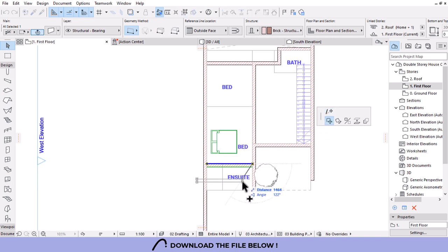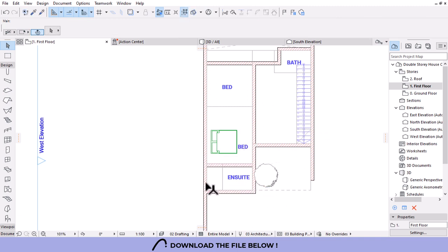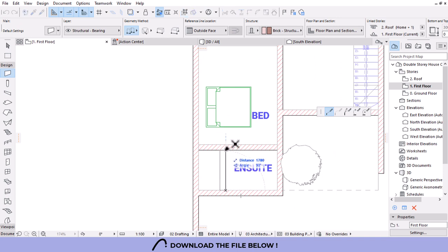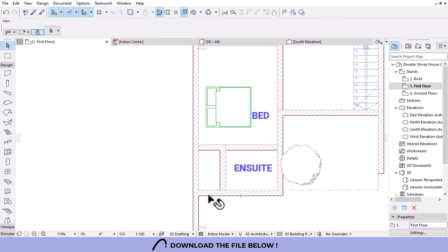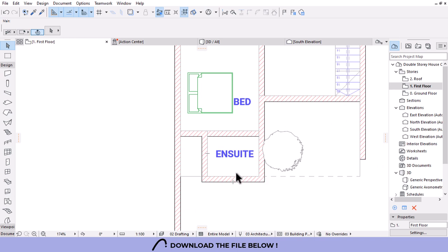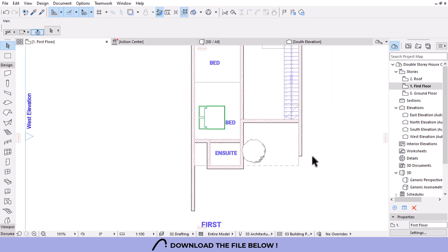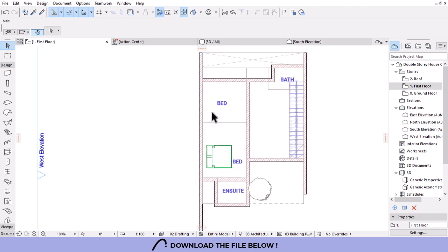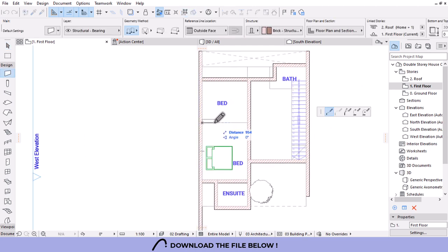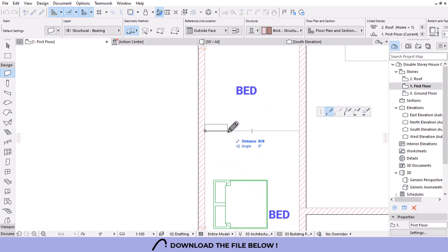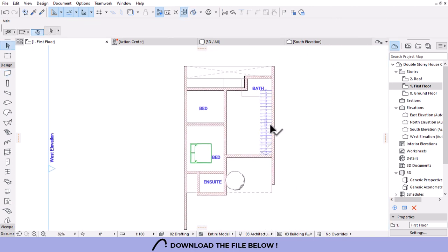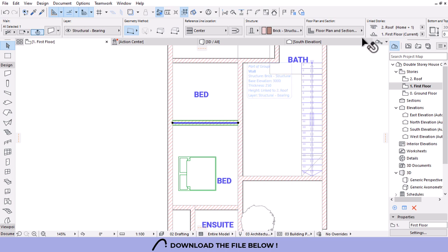and then I'm going to have a copy of another wall there. Yeah, perfect. And then have another one there. Then I can get rid of this by holding Control on your keyboard to activate the scissors. This is a cursor to trim your elements. Perfect. So yeah, I have my insert there, and then I'll have another wall, because this one has to be on the center, so I'll use the center reference line and then draw like that. Perfect. So I think internal walls are going to be 115.